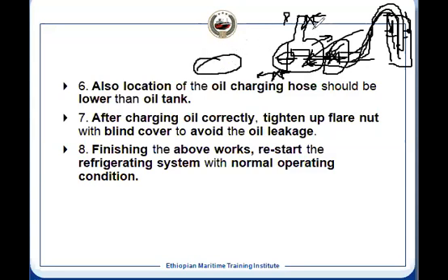This air will go to the condenser, and the condenser outlet is shut. You have the water flowing through it. What will happen? Air is a non-condensable gas. It will be at the top of the condenser. It will get accumulated, being lighter, and then there is a vent provided on the condenser top, through which you can remove this air. You can see whether the air is coming, or your refrigerant is coming.